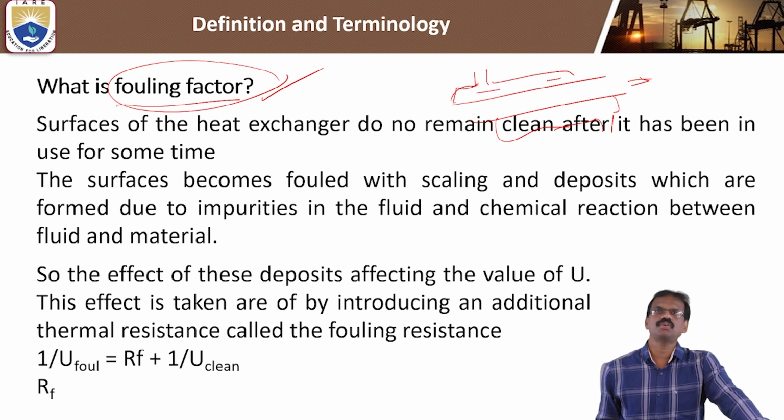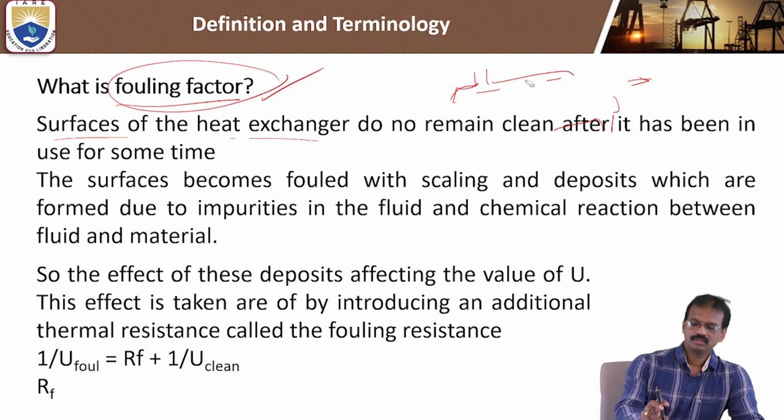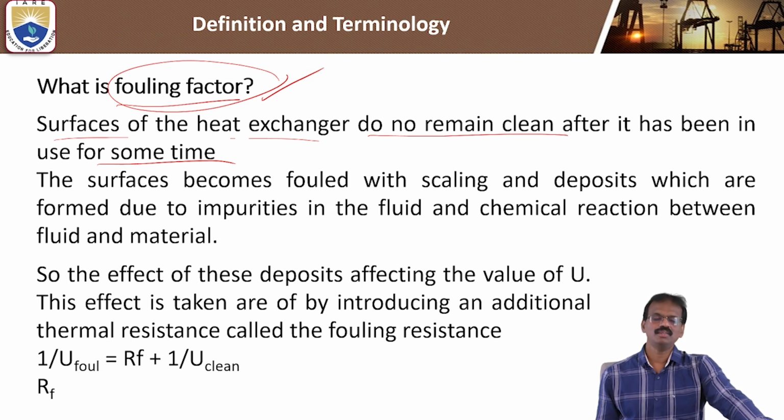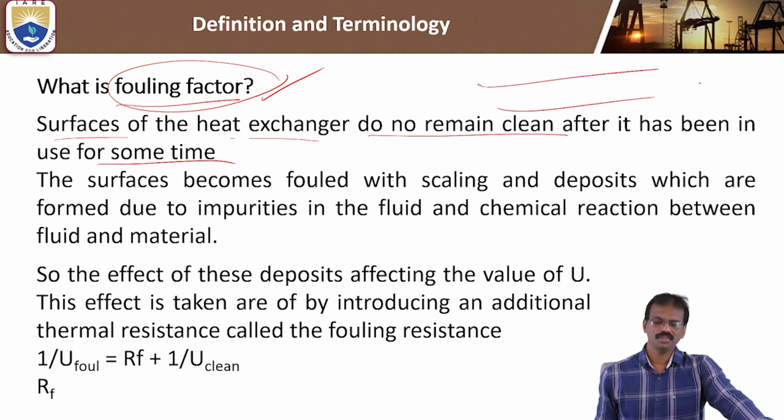We'll see what the fouling factor is. The surface of the heat exchanger does not remain clean after it has been in use for some time. When the fluid is flowing through the pipes, there may be some reaction between the fluids and the pipes, and some type of sludges and scales will form on the surface of the pipes.